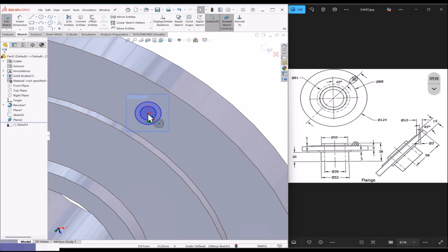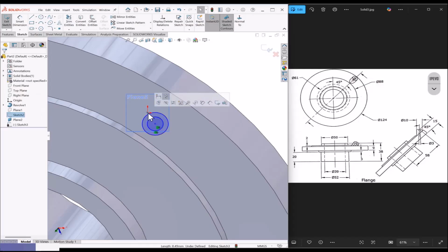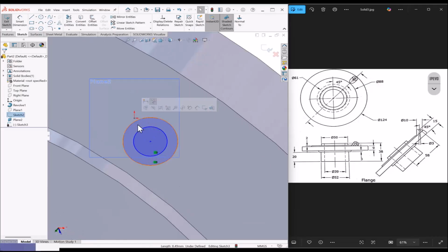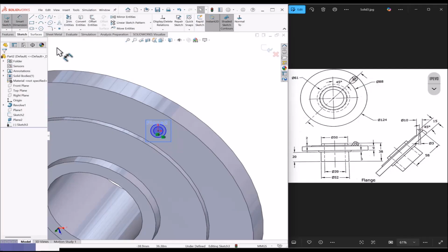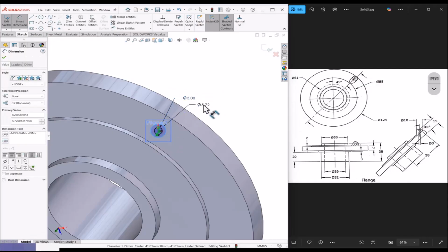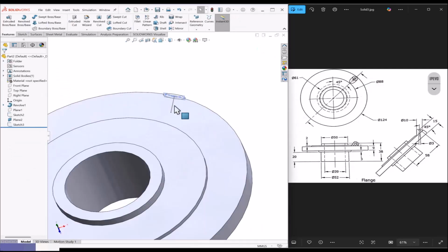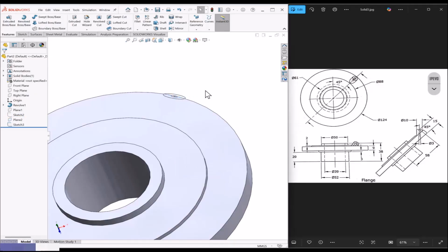And next thing, you can make that point to be coincident with this. So you select this point and select this point and select this point and say pierce. Now define the diameters 3 and 10. Exit. Now you can hide the line because the line is only a reference to take this position. And even you can hide that plane also, no issues. See here.